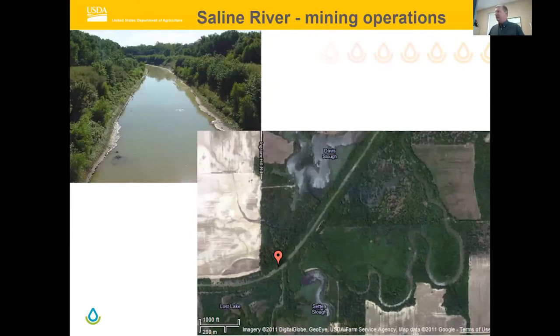We've had channelization of streams, of course, in Southern Illinois. This has led to a lot of long-term issues that we still deal with today, whether it's for mining or other industries. It would take long sections of the original river channel, which you can still see in a lot of aerial photography, and channelize it into a nice straight drainage ditch. And so they took the gradient that was in this length of stream and put it in this length. And when you change the gradient of the stream, we'll talk about in a minute, you upset the balance, and the stream responds certain ways.